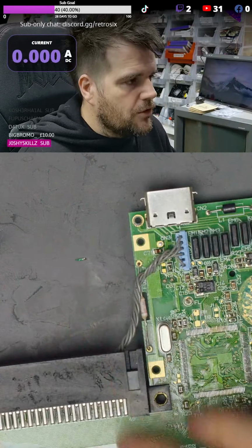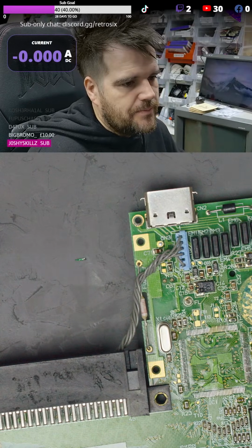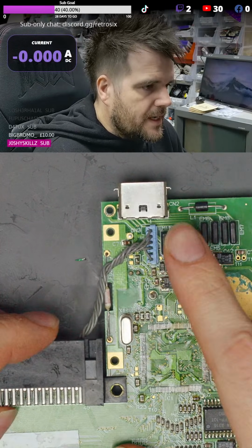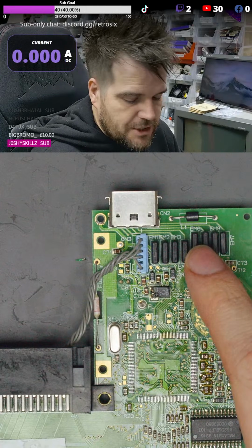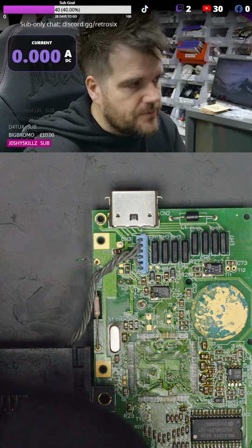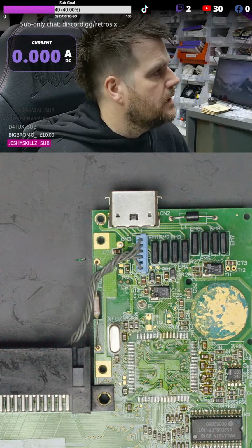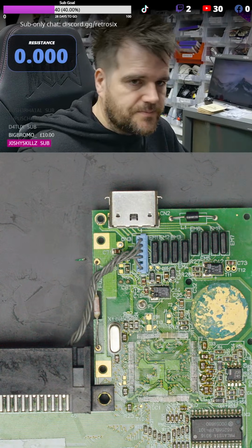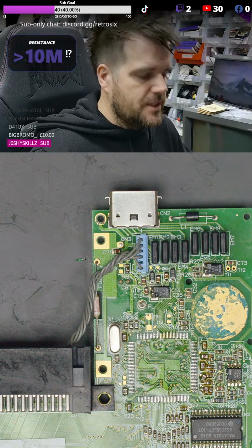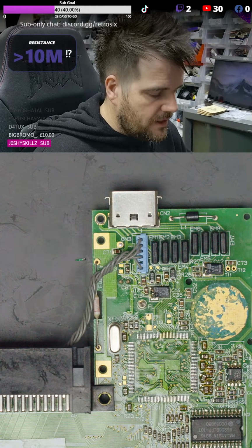You can do other methods. You can try to get things like really, really accurate DC measurements, which we have on this multimeter. So if I pull up the ohms mode on this multimeter, this is a 6-digit multimeter. So this can detect very low ohms.